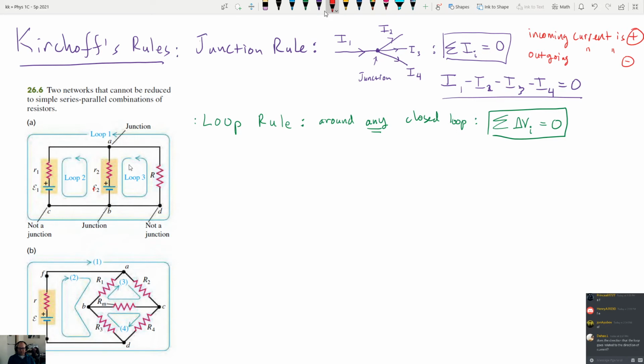So since this source is called E1, I'm going to say that the current flowing in this section is going to be I sub 1. And keep in mind that that same current doesn't just flow up here, it also flows in the bottom down here, and it flows straight through both of these. So this same current I1 flows all throughout the branch from B up to A.